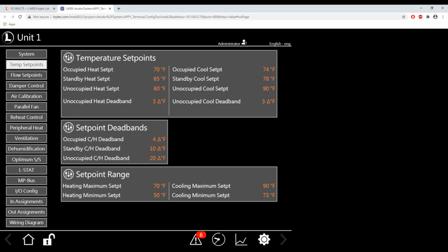Analytics and diagnostics built into the terminal application will notify and prevent unacceptable or improper adjustments of set points via the config tool. For example, when the occupied cool set point is set below the minimum, the terminal application instead sets the value at the lowest value allowed. To maintain the desired deadband separation between the occupied heat and cool set points, the occupied heat set point is then adjusted accordingly. Inversely, if the occupied heat set point is increased, the occupied cool set point will increase as well. Other conditions have been programmed, so keep an eye out for the indicator lines as you configure your device.